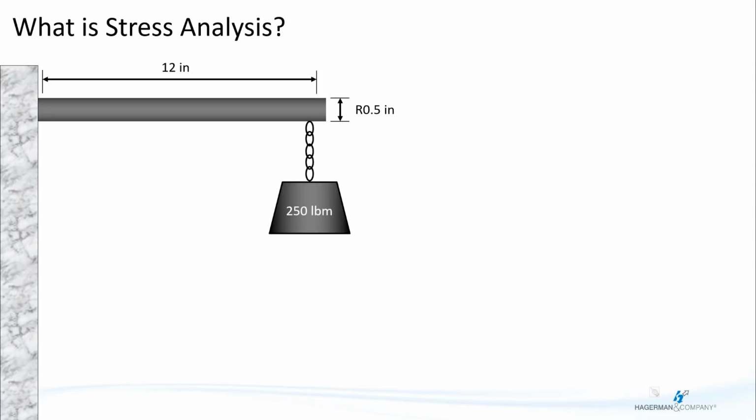So we'll be focusing on the linear static stress analysis type today. We'll also be getting into steady state heat transfer analysis and how the two tie together into a thermal stress problem. The full class will touch on other analysis types, but the focus is still on linear static stress, because it's the most common type of analysis that's run. And it's not quite as easy as you think, and the concepts involved in that typically don't apply to any subsequent analysis type that you'll use.